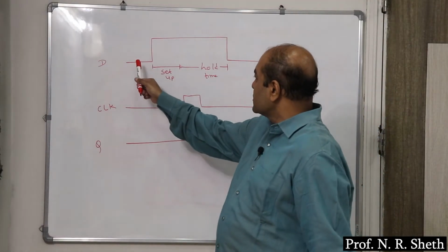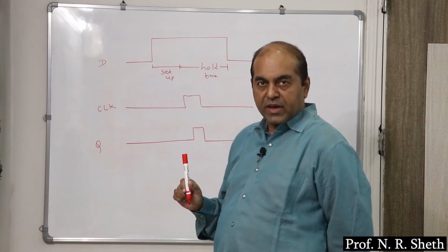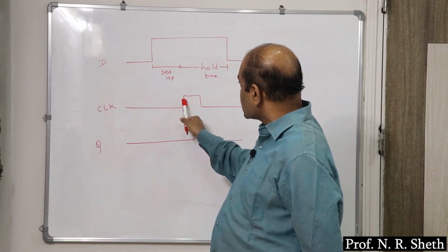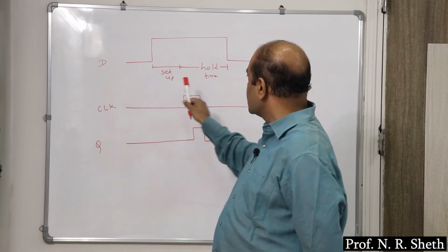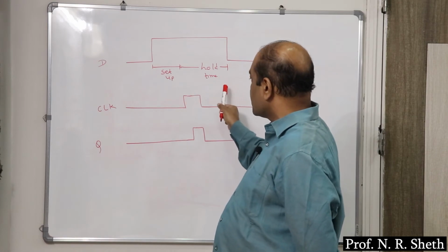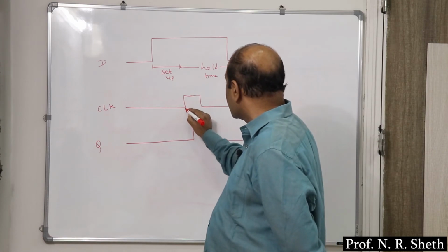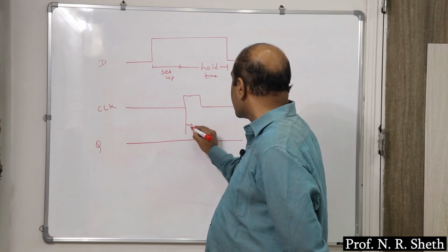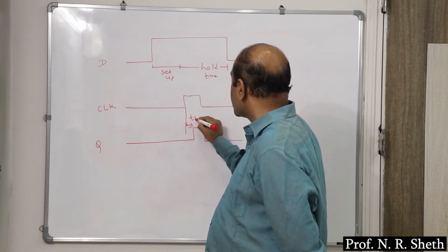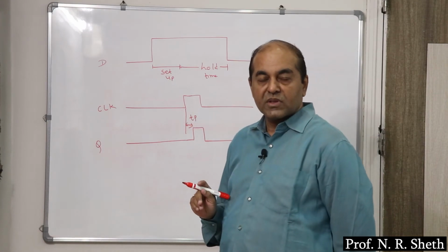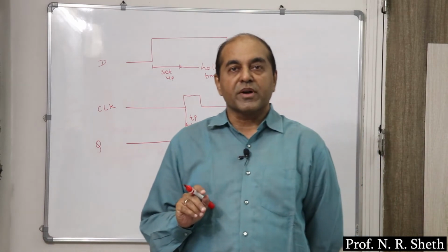This is data input, this timing is known as setup time. This is a clock pulse, the time required before the clock pulse arrives, time required after the clock pulse arrives, and this timing is known as propagation delay time.